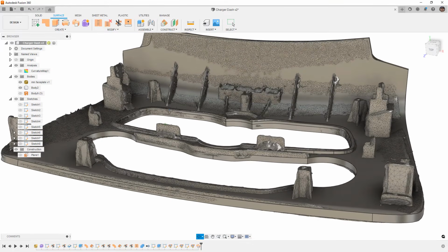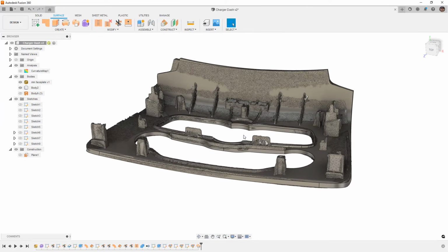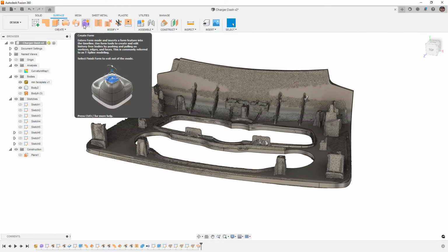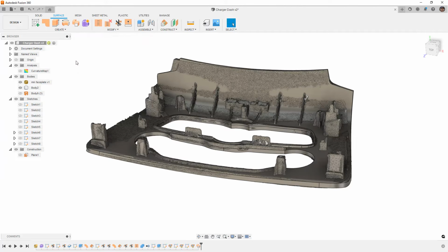But I think for the most part, the techniques that we've covered will let you figure out the resolution of the mesh that you're dealing with, how good of a quality the mesh is, and which direction you want to go. If you have a really high quality mesh, then in the forms, you can use the pull tool to pull vertices down to it and match it. So if you have, like we've done in the past, a high quality scan of a deck lid or a trunk for a car, then you can pull points down so that your end result fits it.